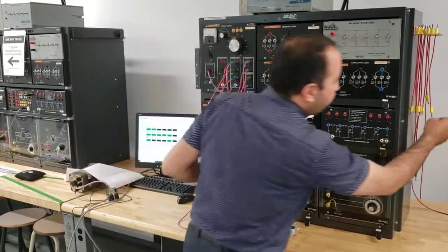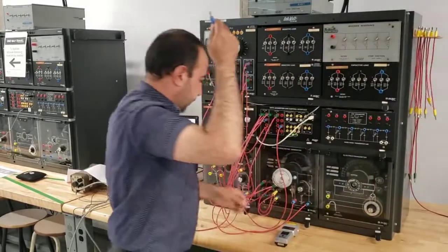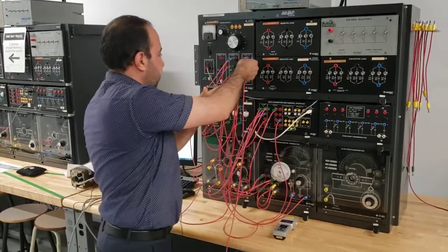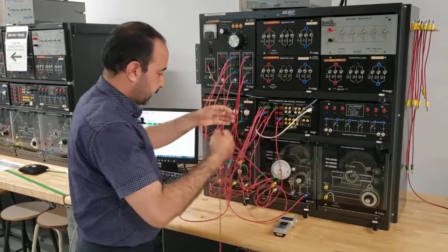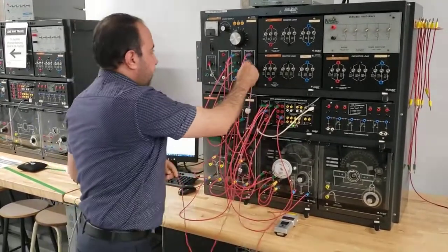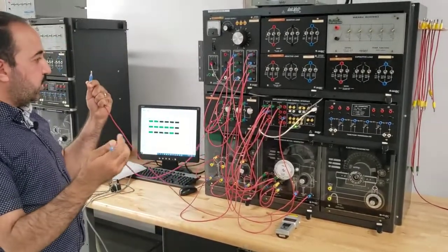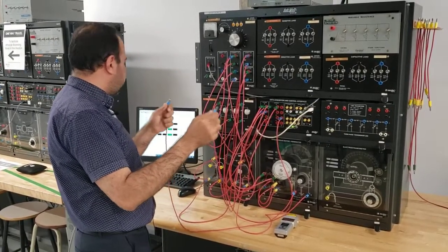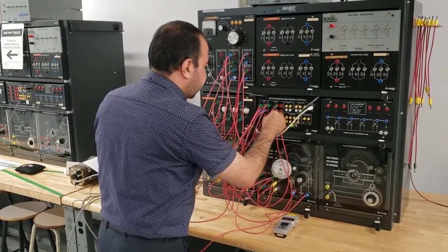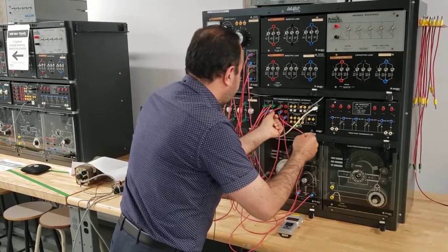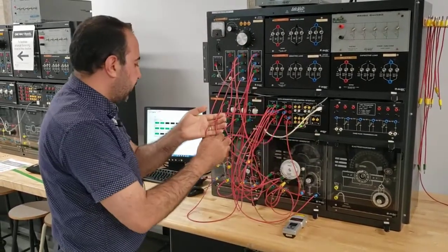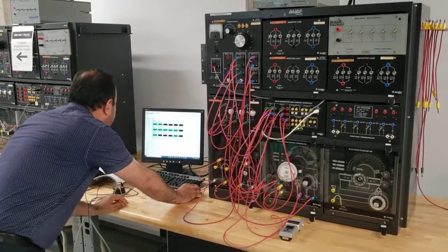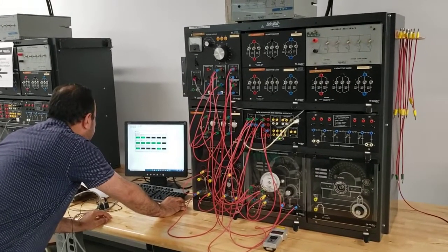So I need one more wire. And what I need here, instead of connecting this guy directly to N, I will disconnect it. And I will put in between these 2 points another ammeter, and this ammeter is DC ammeter because it is measuring the field current for the synchronous generator, which is DC, which is I2, so I will adjust it.